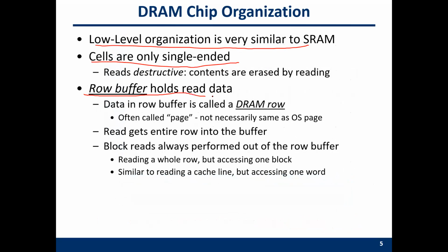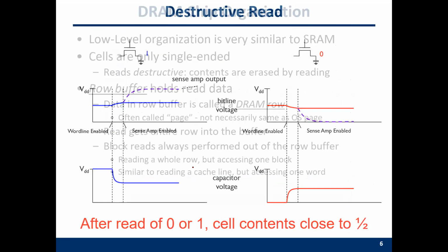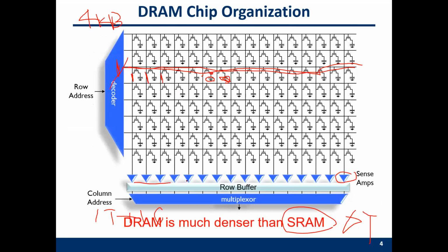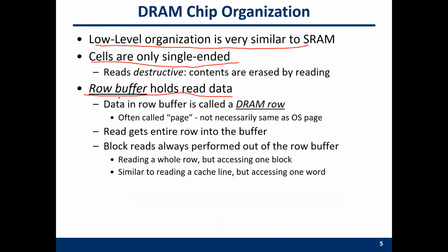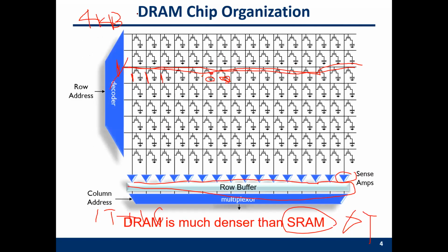And we also have a so-called row buffer. I'm sorry, this is the row buffer. Row buffer is a small buffer which can temporarily store some data for one single row. And we call one row typically a page, because traditionally one row is 4 kilobytes, but now one row may be 2 kilobytes or 1 kilobyte.